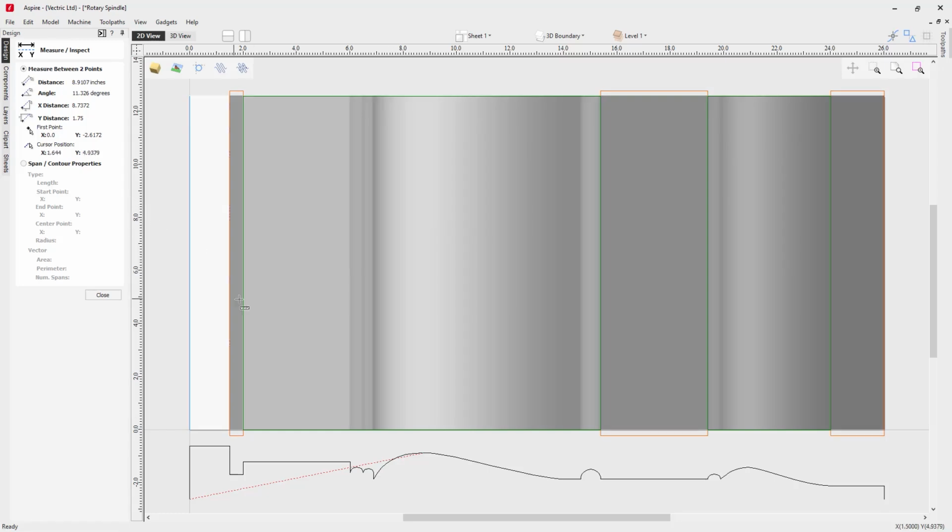3.5. So I've made a note of all these areas. Our square across the flat is 1.4, or 2.8 in total. The lowest point on my octagonal shape is 0.75, or 1.5, and the highest point is 1.75, which doubled is 3.5. So now we can utilize these measurements in our Vector Unwrapper tool. Let's have a look at how we're going to use those in just a moment.